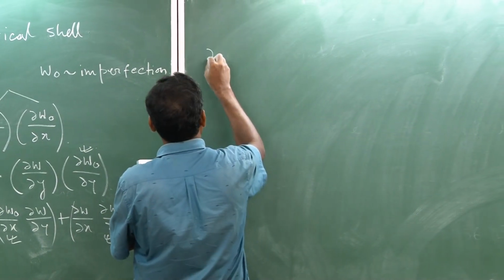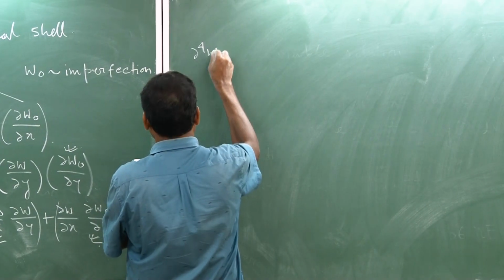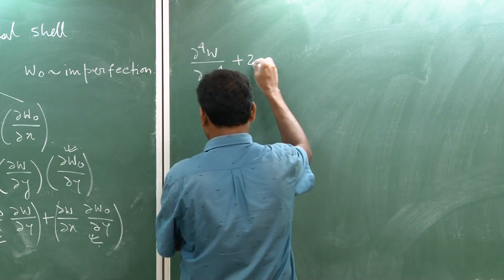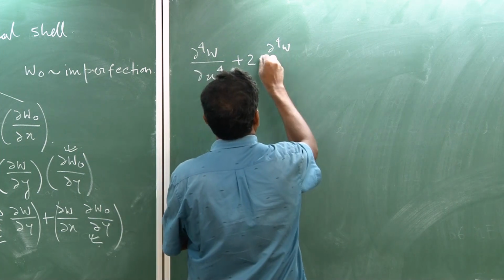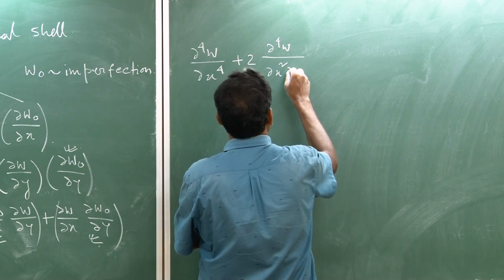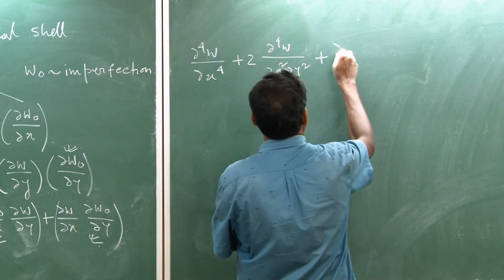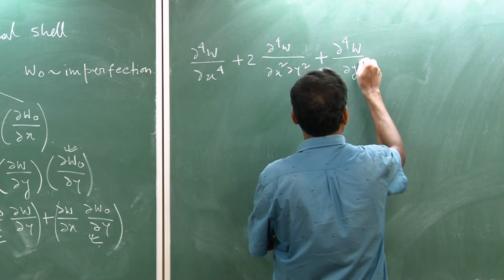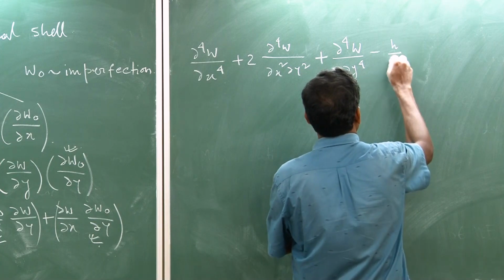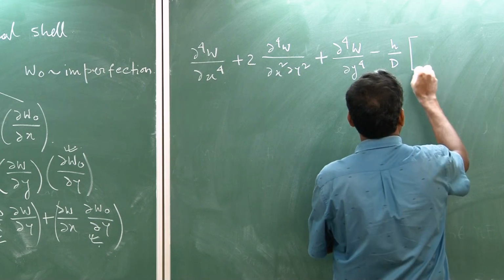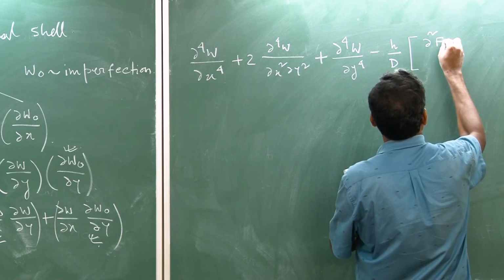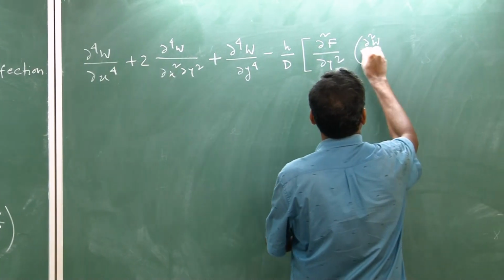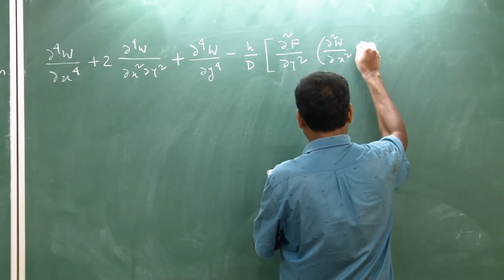So, the one we are going to write: del 4 W del x4 plus 2 del 4 W del x2 del y2 plus del 4 W del y4 minus h upon D del 2 F del y2 del 2 W del x2...